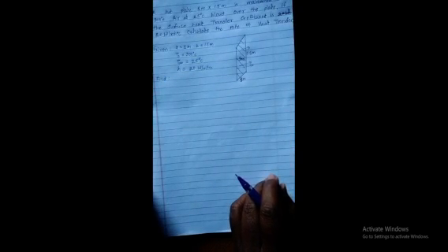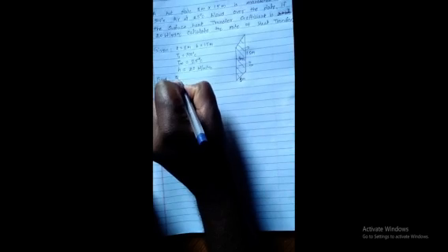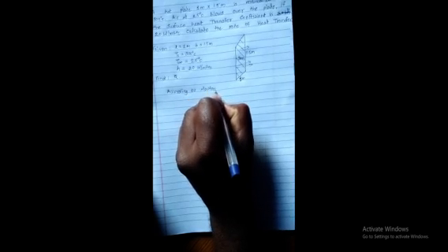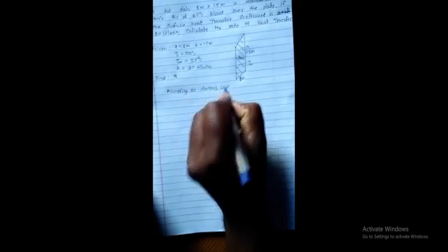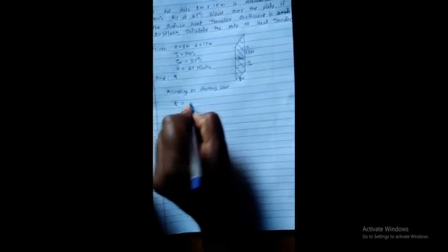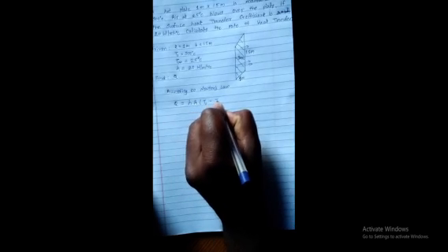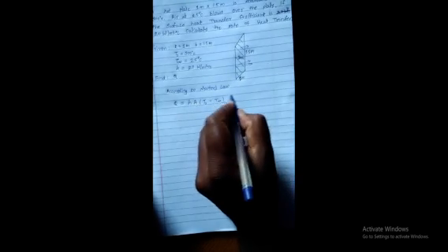Find the rate of heat transfer. Now, according to Newton's law, Q is equal to h into A into Ts minus T infinity.